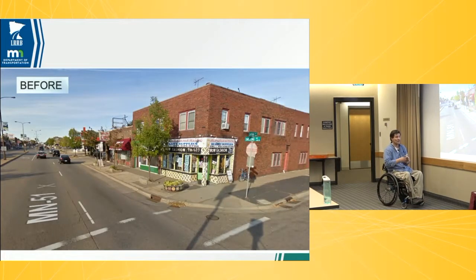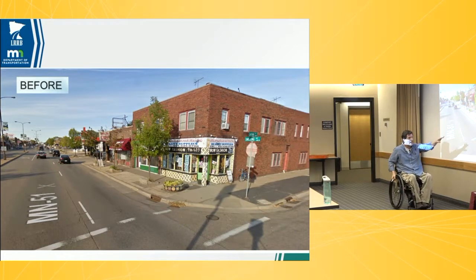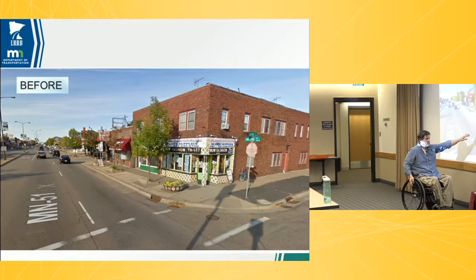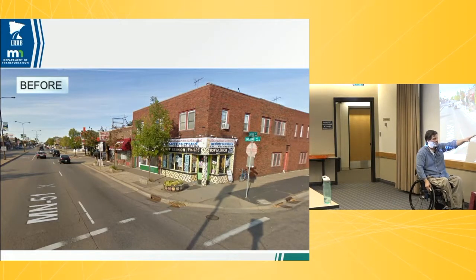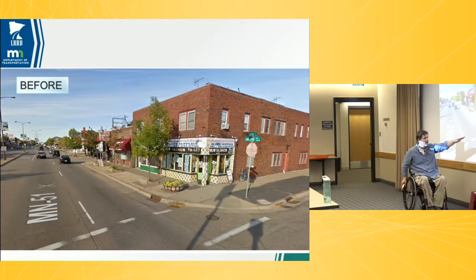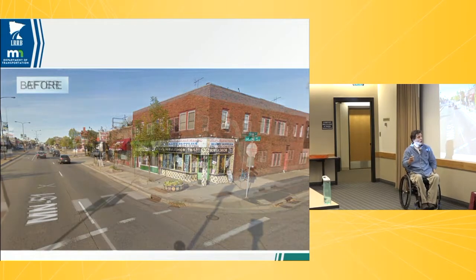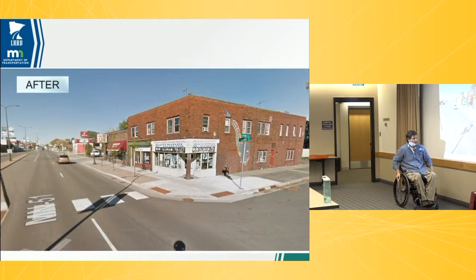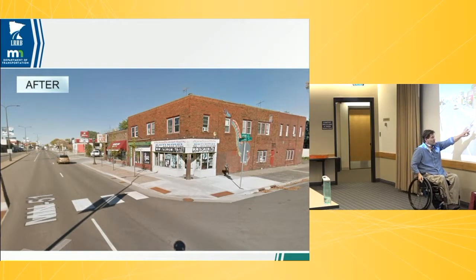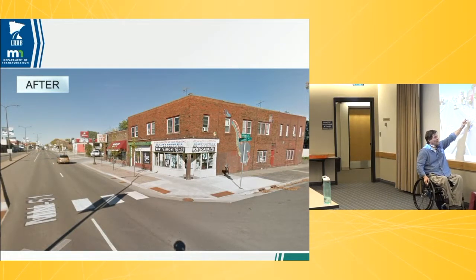Here was a very tricky corner. Again, landscaping all over. We had to tie into this doorway, with 2 drainage structures right in the middle of where your sidewalk would come. We've got our old diagonal type ramp here. This one was tough to get around, with patches all over in the sidewalks. So afterwards, much improved. Those 2 structures, we relocated them out of the way, allowing that curb ramp to come in there, directional curb ramps both ways. But actually, we've got a couple structures over there.